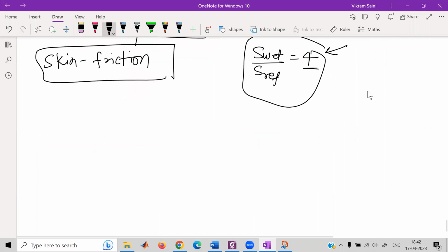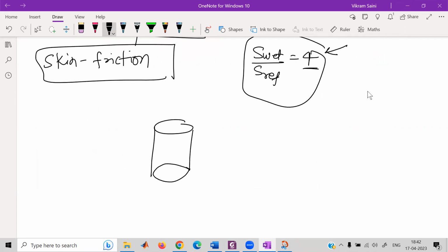In simple language, let's consider a cylinder. Air is coming at the front, going like this. Skin friction comes because of this interaction between air and the skin. But the pressure drag comes because the velocity of air stagnates, right? If I just look at the incompressible regime of the flow, then pressure at the stagnation point is certain pressure, let's say PA and PB.